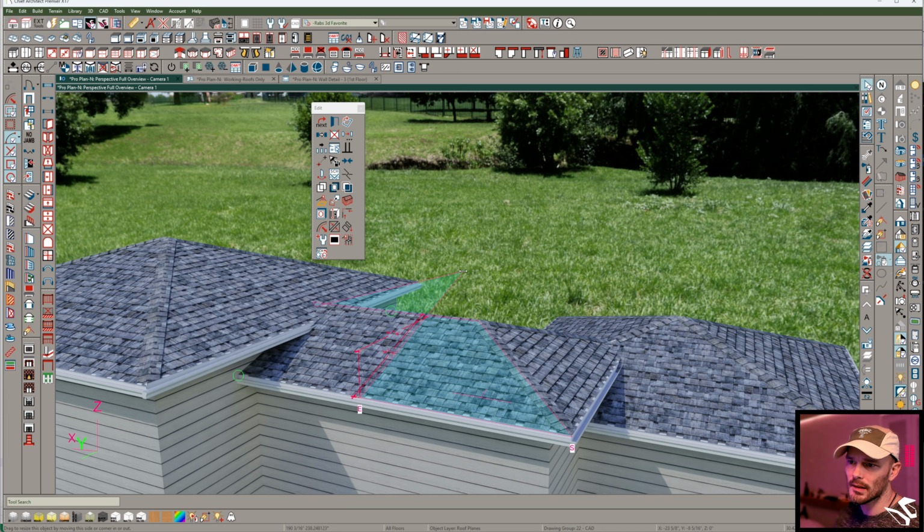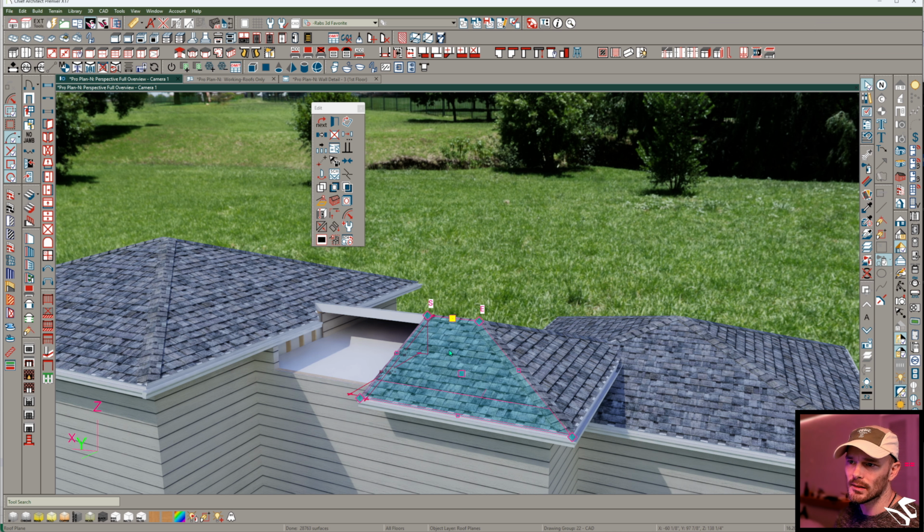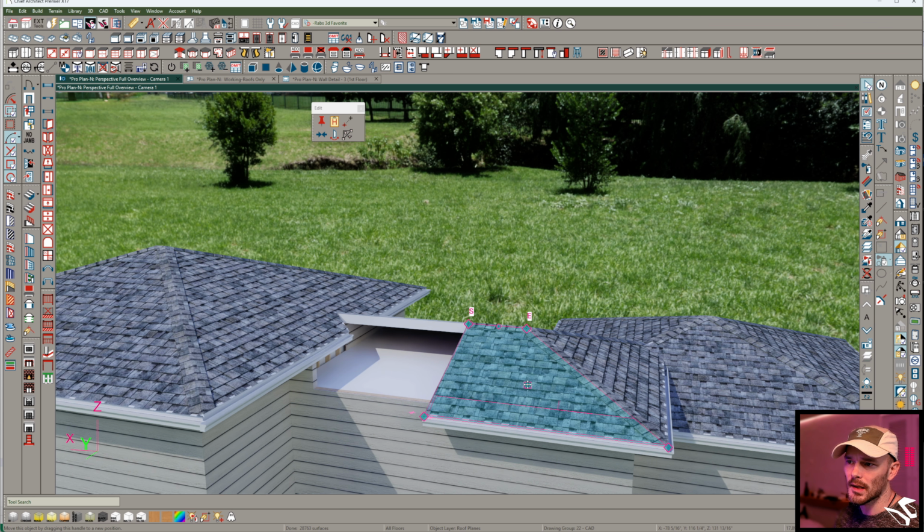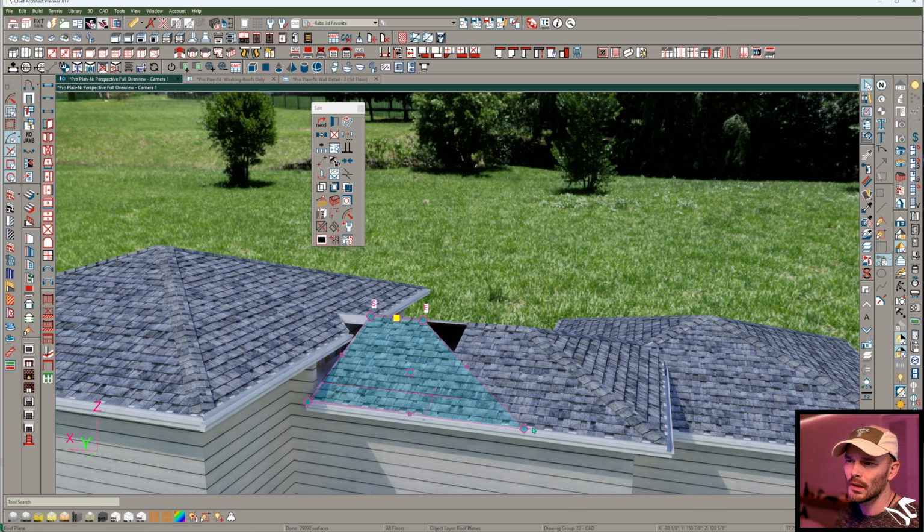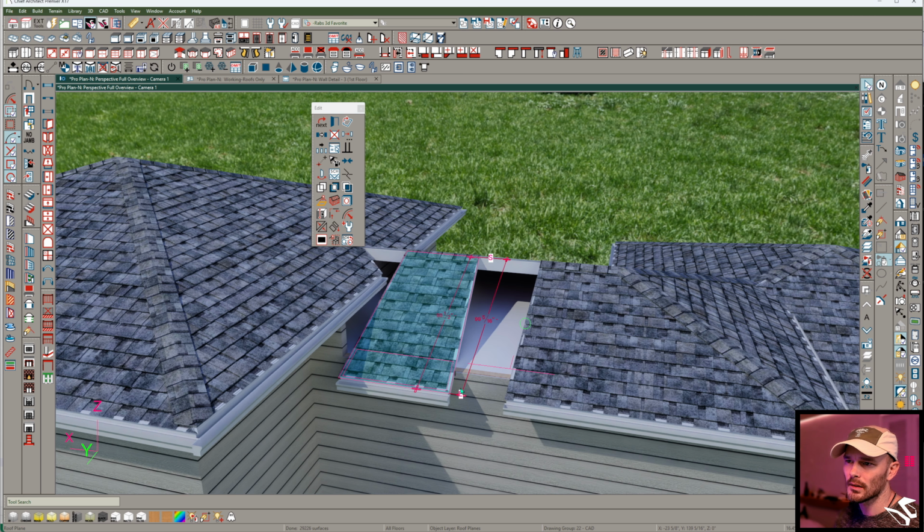When I cross it like this, it's going to cut the excess, right? And then we'll copy paste this forward, bring this forward a little bit, and we're going to end up copy pasting this to the other side as well. I don't care that this isn't at a 90 because I still get to use that join roof plane tool to kind of conform this, maybe? No. And the other thing we can always do is use that